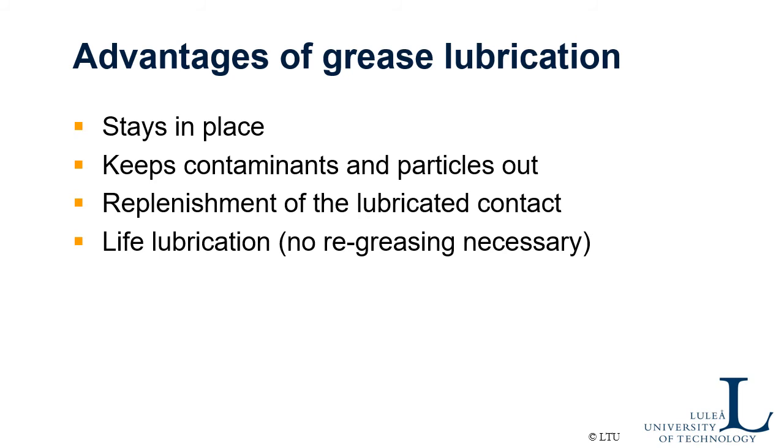First of all, since it's semi-solid, it stays in place. So if you fill a rolling element bearing with grease, it stays there for a longer time than putting a fluid there, which will flow out pretty soon. And since you have a grease there and you have some solid stuff in the bearing, you also keep contaminants and particles out from the bearing.